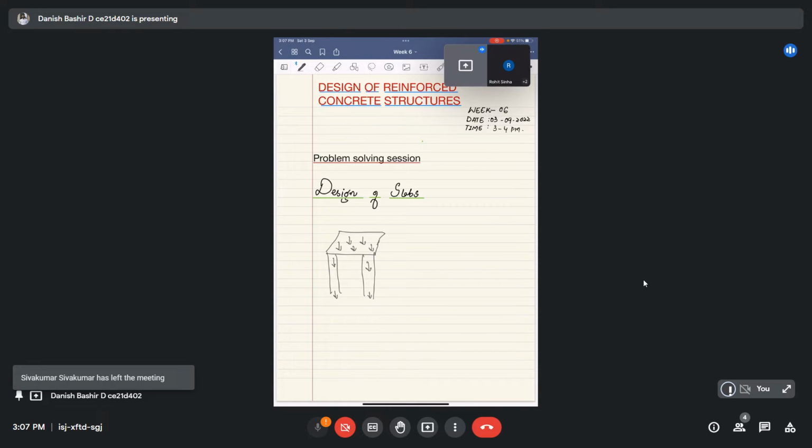In technical language, we call these slabs diaphragms. They also help in maintaining the stiffness of our structure. Due to the high in-plane stiffness of these slabs, they give a lot of rigidity to our structure when it is subjected to transverse loads, for example wind load or earthquake load. They play a very important role in stiffening the various vertical frame elements.